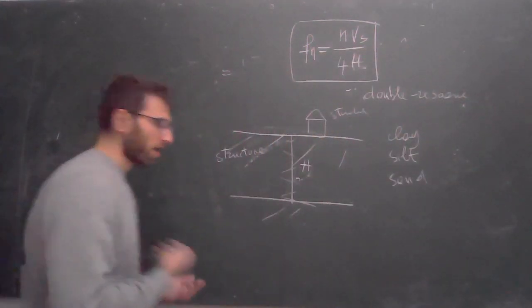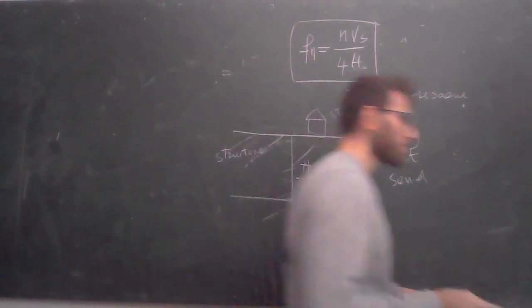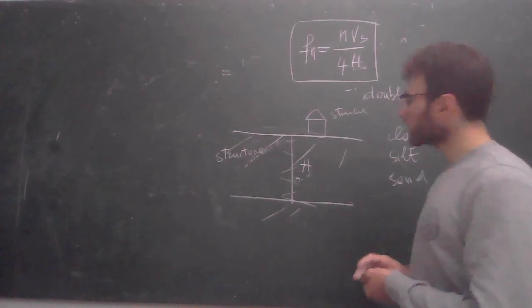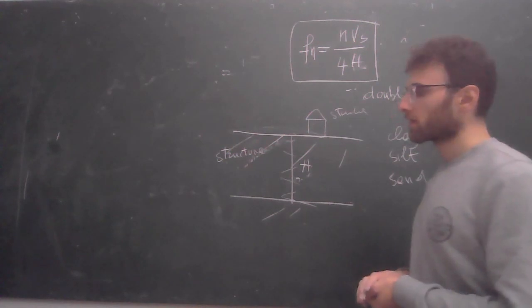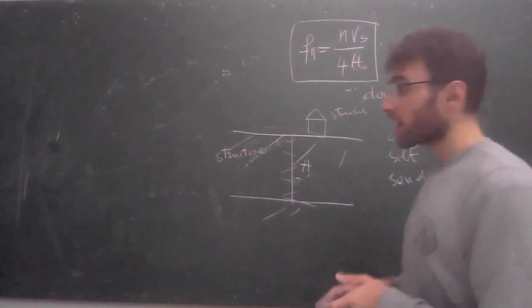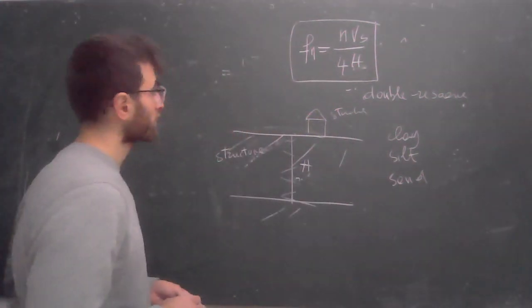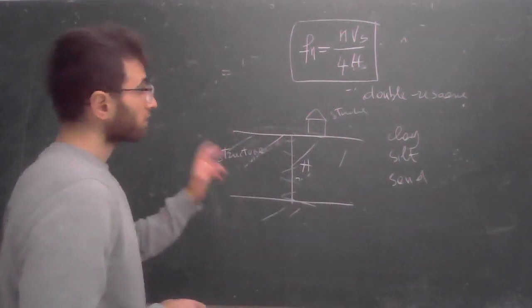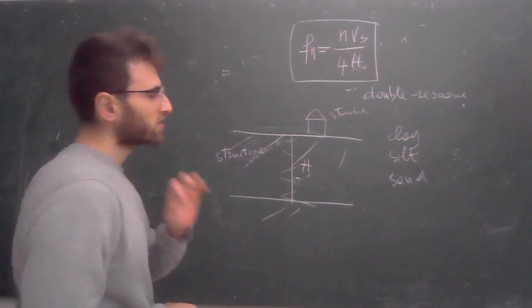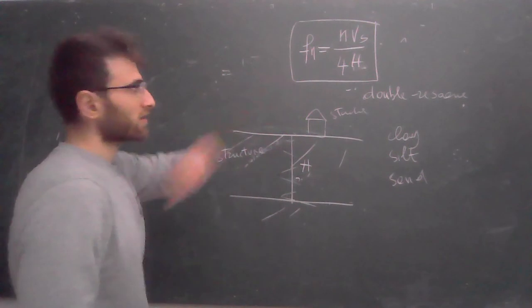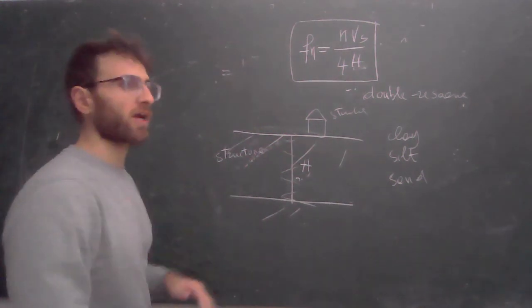I mean, there are immense assumptions. But simplified equations are very useful to understand phenomena, very useful. So many geotechnical engineers remember that equation, Vs over 4h.